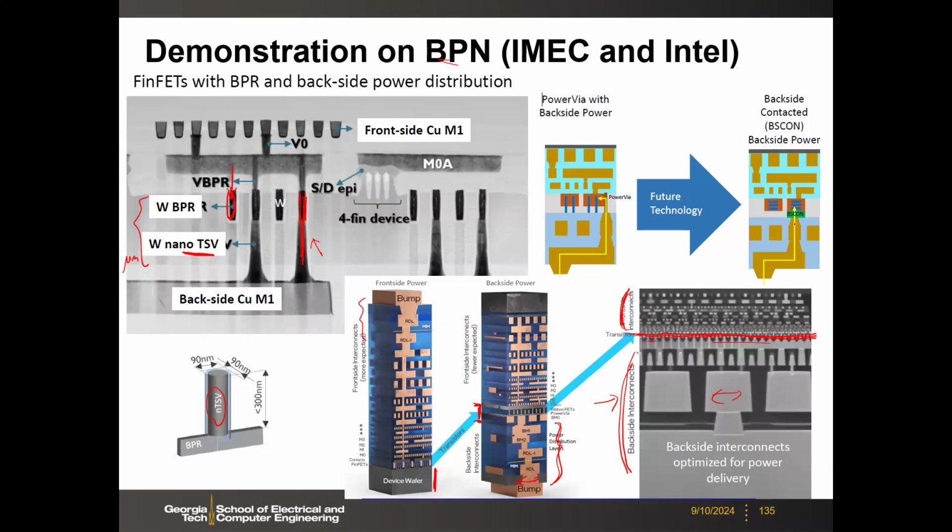So the ultimate goal is to have this backside power delivery directly attached to the back contact for the stack nanosheet. Let's say the source and drain will have the direct backside contact. Therefore, you can have the VDD and VSS powered in from the backside direct contact. This is not there yet. This backside direct contact is not there yet. It's on the roadmap.